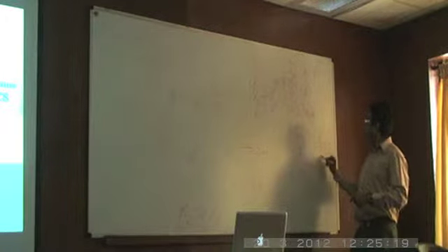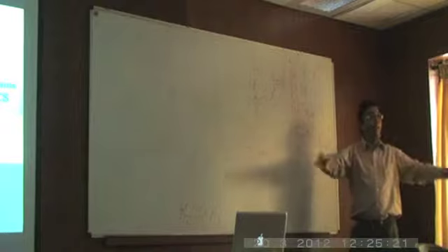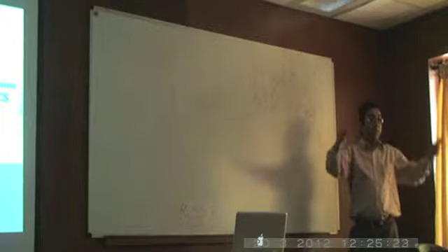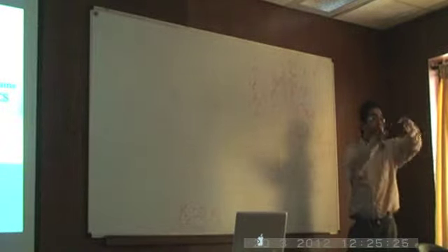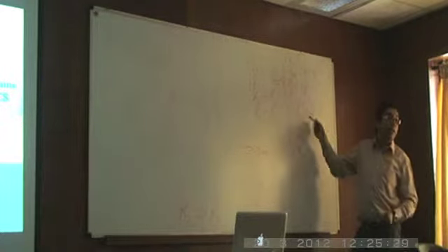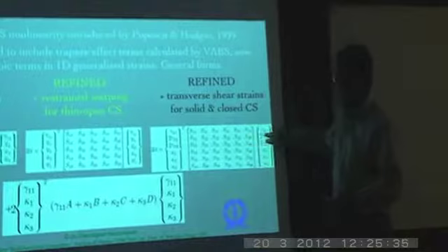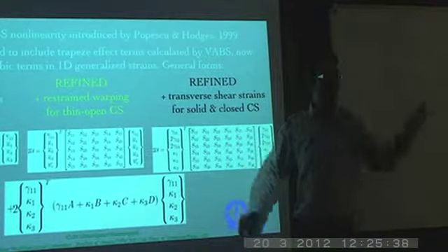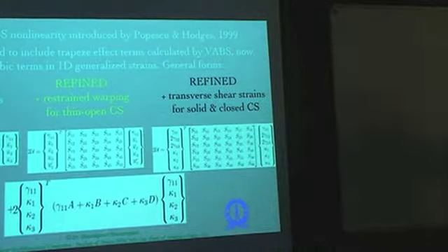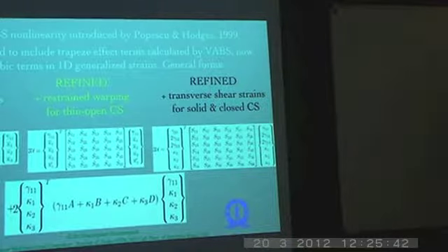So basically your epsilon alpha 3, where alpha takes on the values 1 and 2, where 1 and 2 are the directions in the plane of the plate or in the mid surface of a shell. Associated with that, you will get those additional terms. That is equivalent in the beam sense to what you have over here. That is for thick plates and thick shells. You will get the effects of these kinds of quantities.